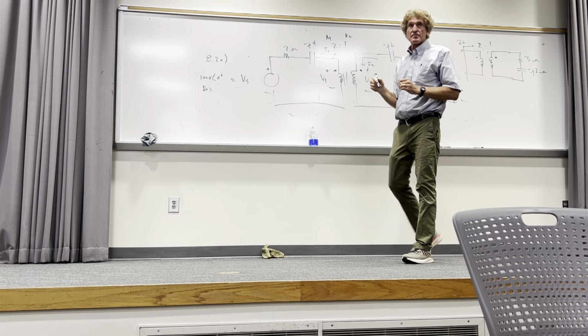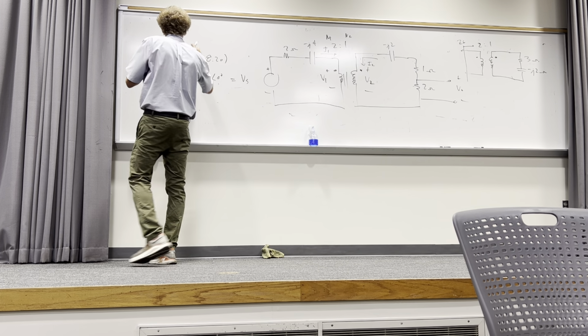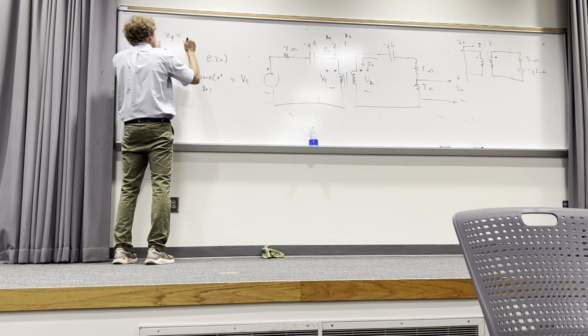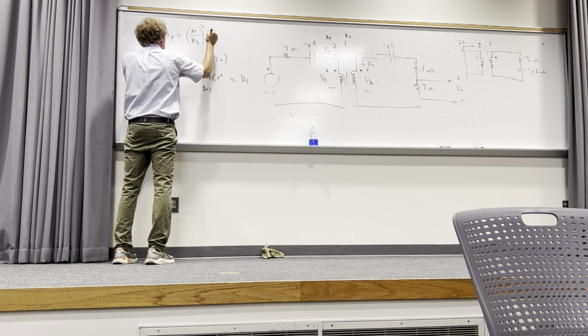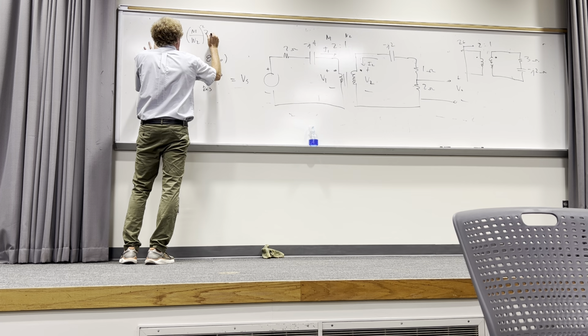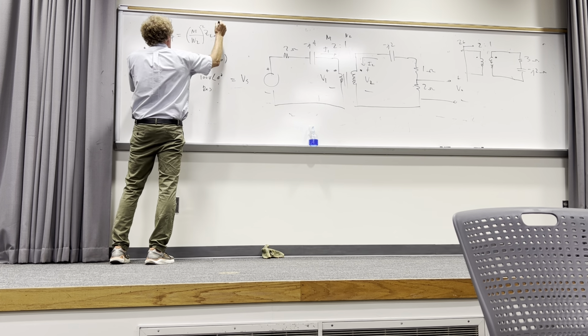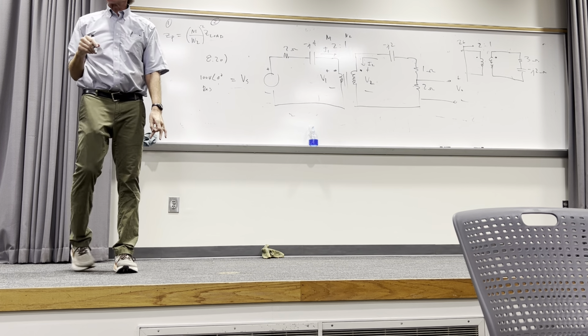Clear? Can everybody follow me? Now the equation says this. Z primary is equal to (N1 over N2) squared times Z, and I'll call it load, or the secondary. This would be on the side of the primary. This would be on the side of the secondary. Can everybody see that? Amanda?